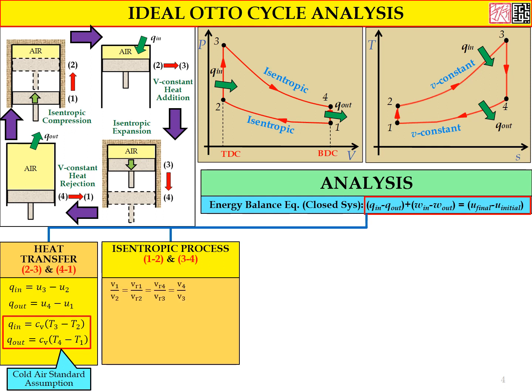So we have this ratio V1 divided by V2. Small v represents the specific volume. The unit will be meter cubed per kg. So V1 divided by V2 represents the compression ratio. We call the ratio the compression ratio. And VR in the equation refers to the relative volume, and we can get this value from the ideal gas table of air. And this parameter VR has no unit.